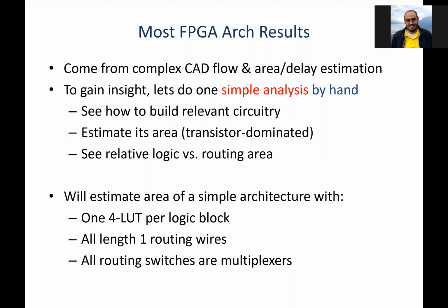Okay, so we're going to start looking at... We went through three kinds of FPGA architectures. We went through a few logic element architectures. We saw LUTs really dominate. Then we went through different ways you can organize the interconnect, and island style, nowadays mixed with some hierarchical routing for the logic blocks, dominates. Now, if we want to go further into more detailed quantitative results, you have to put together a complicated CAD flow and area and delay estimation.